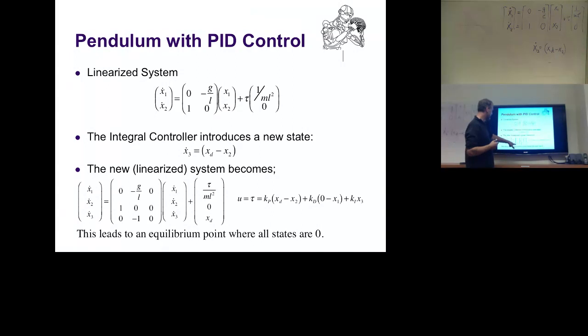So x3 becomes a new state which changes over time. And now we can essentially insert x3 in our system of equations. So we need a new state variable. That's very important. We create some kind of hidden novel state which does not really exist. It's a control state which we need. So we basically create x dot 3 now here. Now I can finish my matrices.